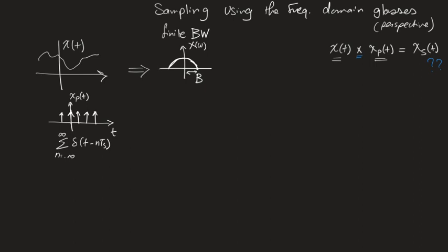When we moved to the Fourier transform, we said it's a more generalized transform that allows you to deal with aperiodic, but also you can still deal with periodic signals. In the special case that you use the Fourier transform on a periodic signal, it produces delta functions with certain amplitudes, and those amplitudes depend on what your time domain signal was. They can have values that correspond to the Fourier series coefficients, but that doesn't matter to us now.